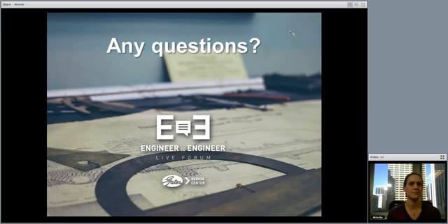Another question, does NEMA apply to gearboxes? So no, NEMA diameters only apply to electric motors. However, you do want to check with your gearbox manufacturer. They use something called overhung load. And so you want to take the drive and check with your gearbox manufacturer to make sure that the shaft loading is within the limits that they set.